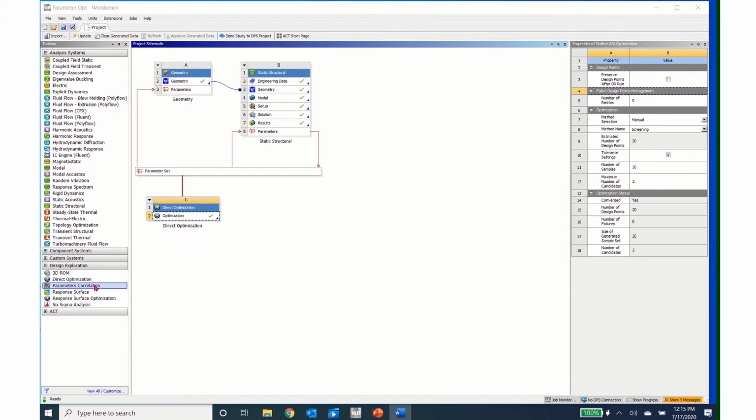The parameter correlation tool allows us to identify the parameters that affect the variables of interest and identifies the degree to which the variables are affected. A sensitivity plot shows what particular quantities are sensitive to. The response surface tool uses design of experiments methods and takes weighted inputs from the parameter correlation analysis and distributes sample points optimally within a bounded design space.